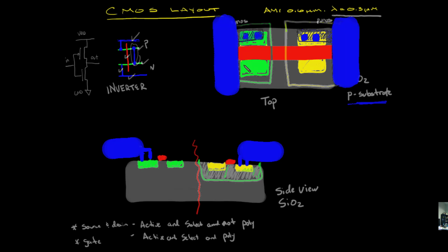And we're going to do that with one more set of vias and another metallization, another metal 1 layer that kind of goes and connects these guys. And so that would almost complete everything. We have one more step to complete, and that is we need to complete a via from the poly silicon down here for the gate and another metal connection.